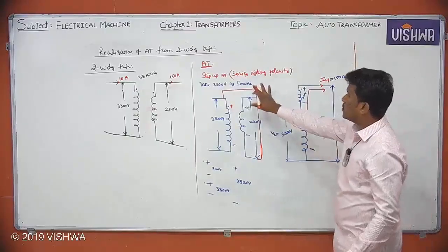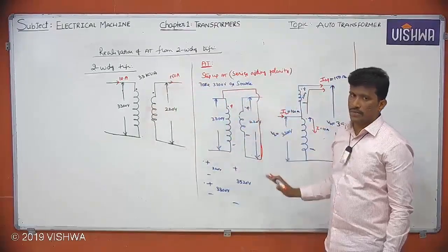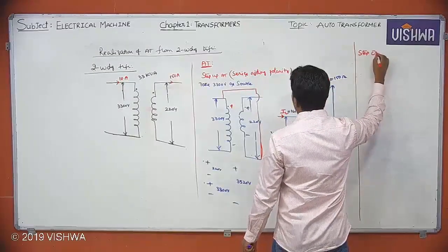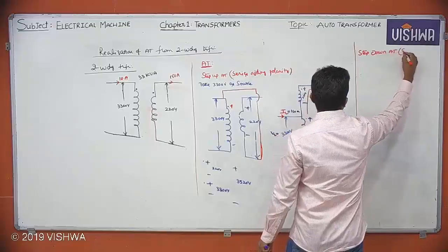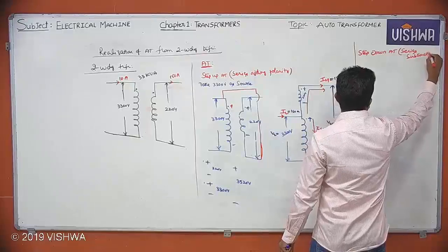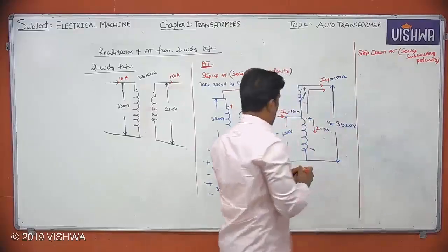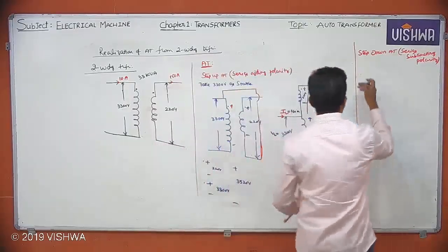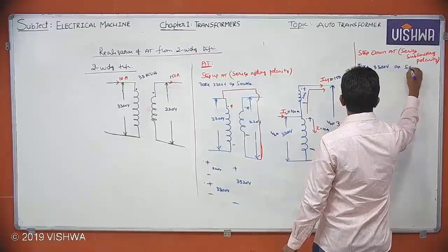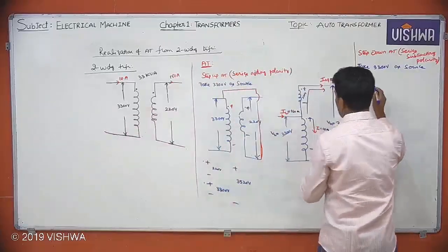Okay. Next, this is regarding the auto transformer. How I am modifying an auto transformer from a two-winding transformer, that was step up. Now please tell me, for the step down auto transformer, what does it mean? Series subtractive polarity. I'll give a hint once again. Take 3300 volts as source. Once again, this two winding, please try to draw once again here.